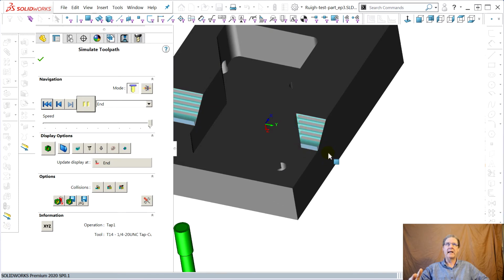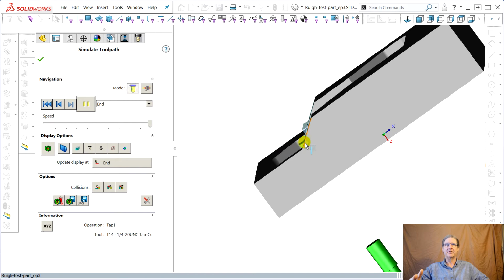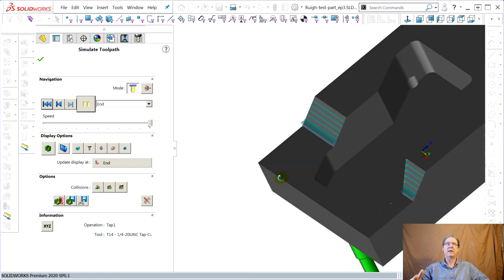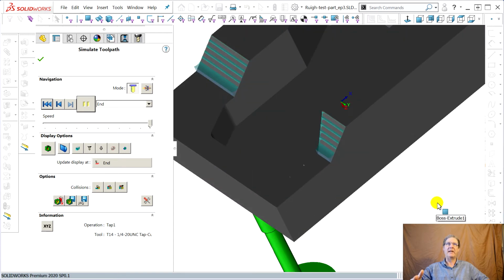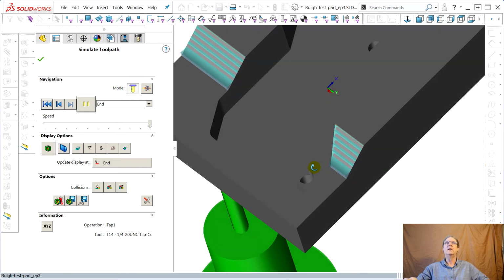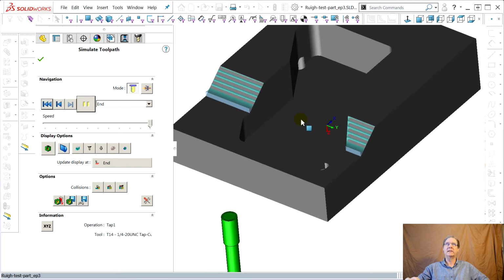The little scallop's going down leaves a big scallop here, and I'll show you why the tool has to do that. This is where you'd use what they call a pencil mill to go in, a real tiny 1/8, 1/16, and just get this sharp corner here. But okay, I'll trust that. But it's still not what we want. It's not fine enough, right? It's a little too coarse.